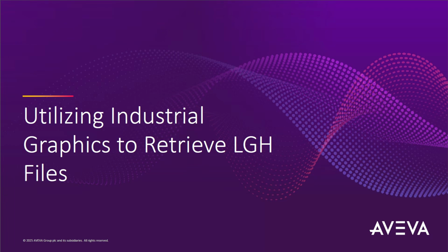In this video, we're sharing a clip from a recent session where we demonstrate how to use industrial graphics within InTouch to retrieve and display data from LGH files. If you're looking to visualize local historical data directly on your HMI screens without needing Historian, this is a flexible and user-friendly option. We'll walk you through how to configure it, link it to LGH files, and present that data clearly to operators. Let's get into it.